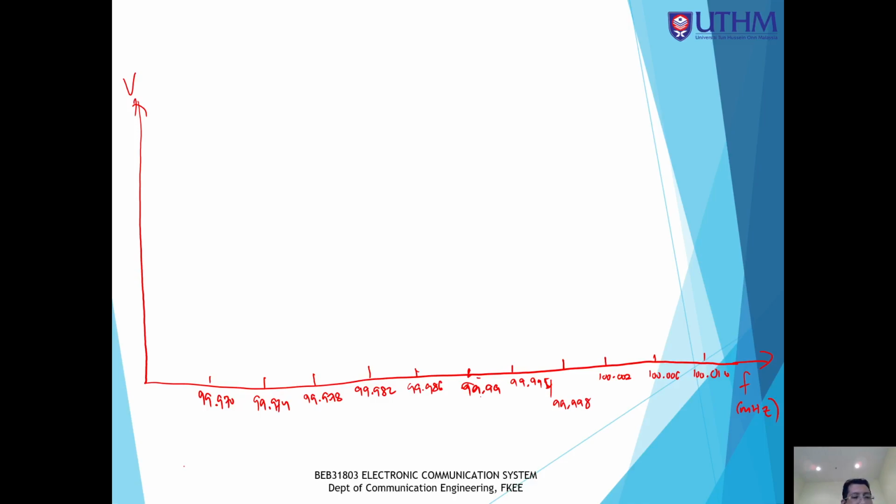Okay. So when you want to draw the spectrum, here the center is negative 0.25. And then the first sideband is 2.5, so you can estimate, for example, at this height, 2.5 volt.